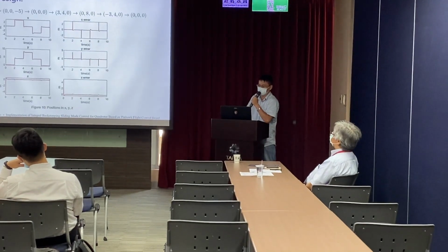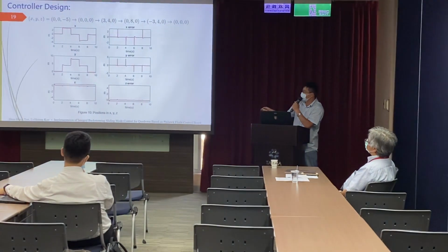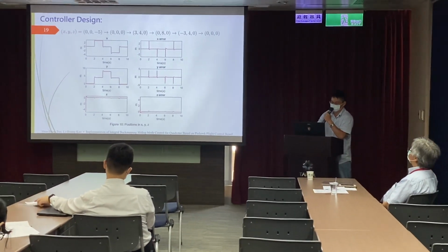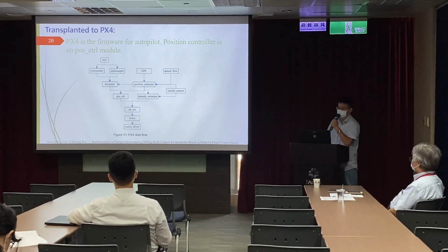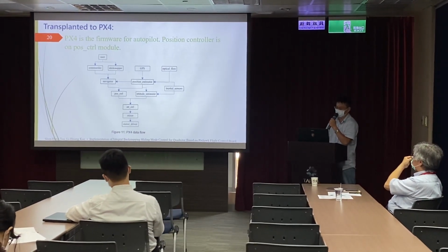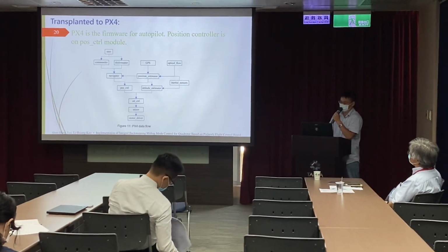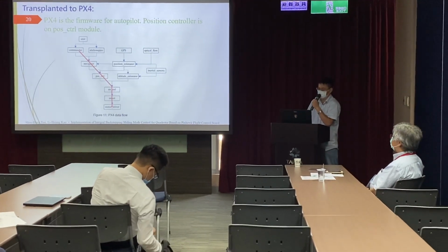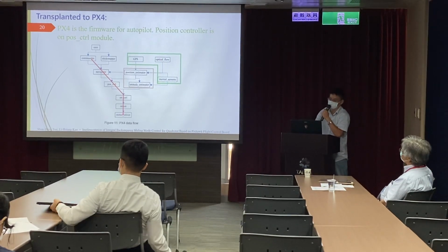And figure 10 is the position of the simulated flight. As you can see, when the target changes, the quadrotor could quickly reach the target. Then we start to transplant the controller into Pixhawk, and we are using PX4 as firmware for Pixhawk. On each application layer, the controller runs from the user command down to the motor spin, and its data relies on the data mining process using its sensor devices.